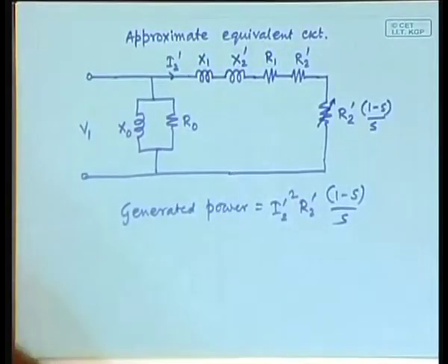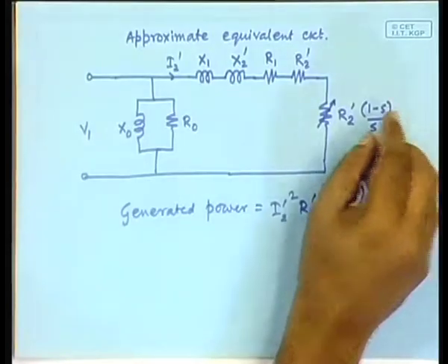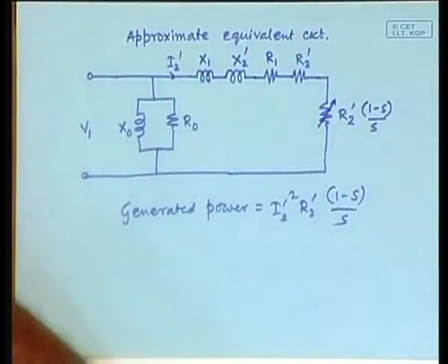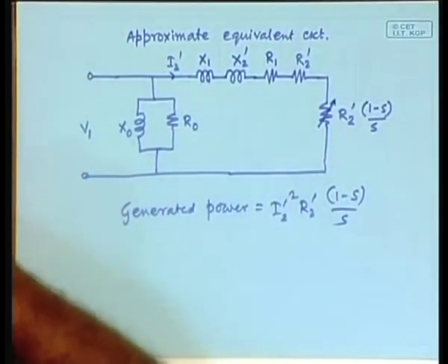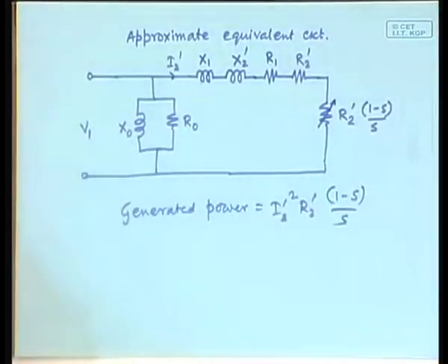That is what we needed for the wind turbine, right, because otherwise you cannot attain the maximum CP value. In order to attain the maximum CP value, the tip speed ratio has to be constant, and therefore, as the wind speed changes, you have to keep changing the rotational speed, which means omega r, which means s. So, all the time s will vary, but the frequency will not vary. So, it will still keep on pushing power into the grid. That is the main advantage of the induction machine in comparison to the synchronous machine. Okay. Fine.